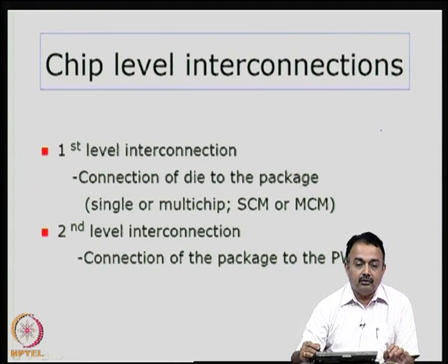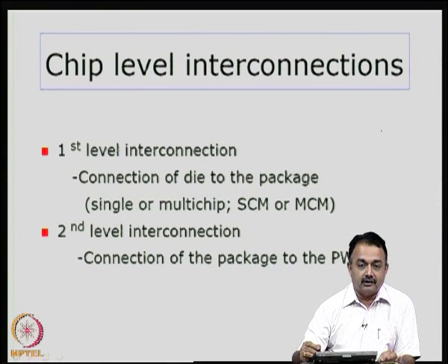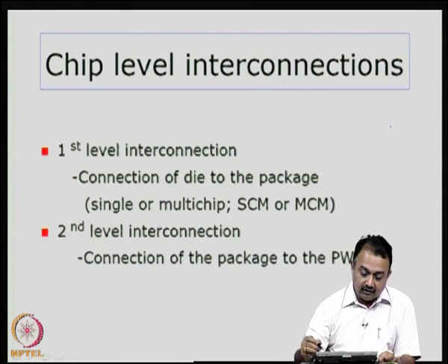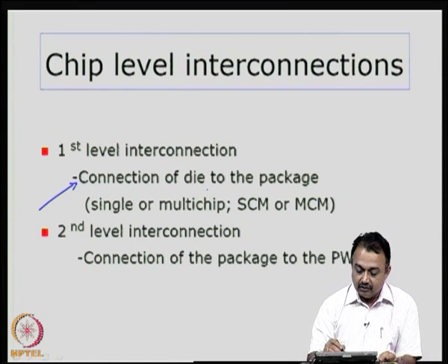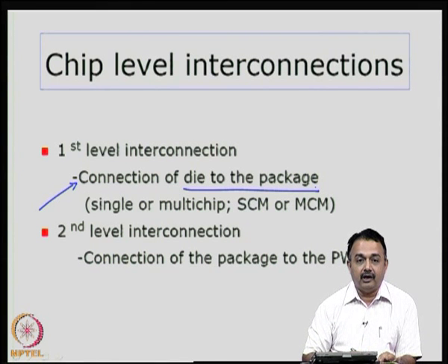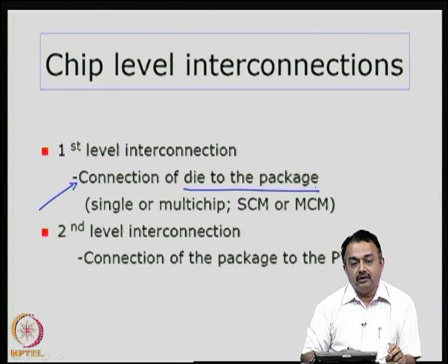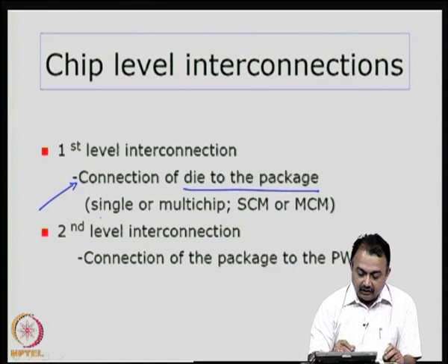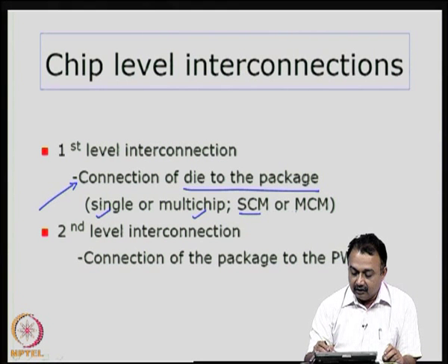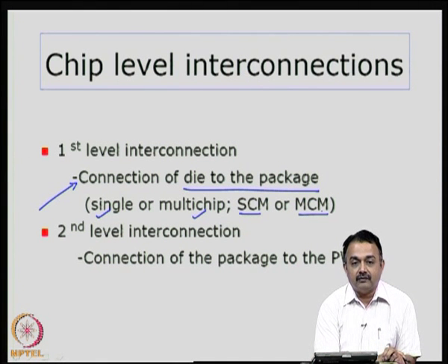We will move into some details on chip level interconnects, or first level interconnections. The first level interconnection, now you have a better idea, talks about connection of the die to the package. Basically we have to look at how you can connect the bond pads of the die to the package substrate. As the result of this first level interconnection, you will get either a single chip module or a multi chip module, SCM or MCM. SCM stands for single chip module, MCM stands for multi chip module.